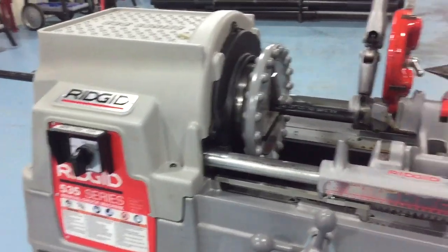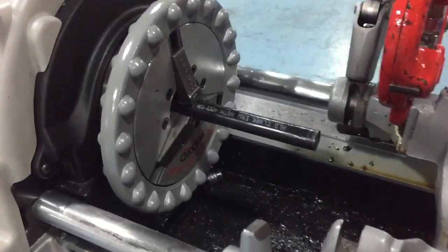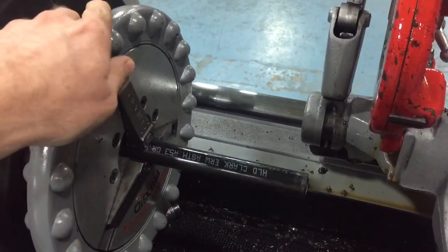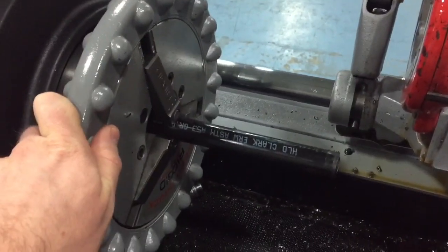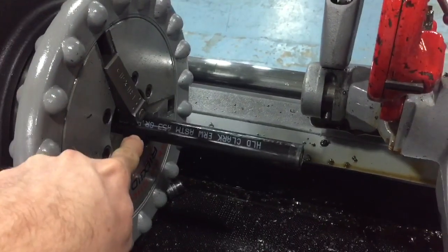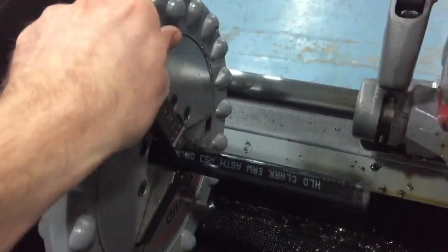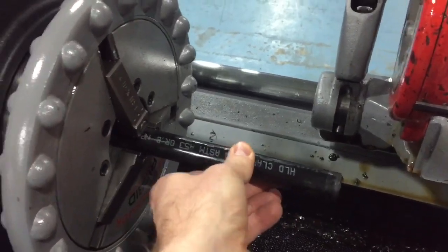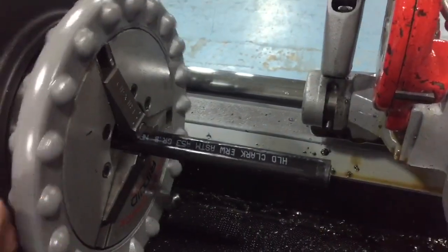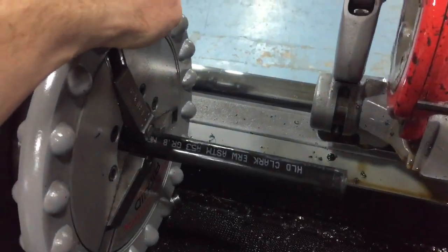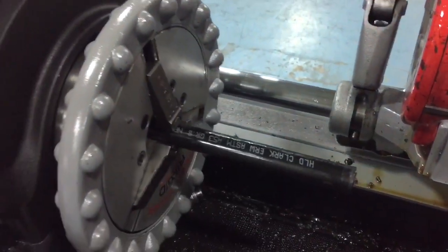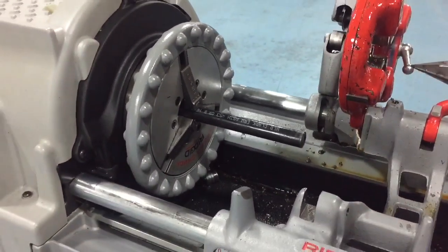So what we're going to do first, I have the pipe in place here. It has a chuck. We hammer it and it grips the pipe, the chuck right here you can see. And so if I just hit it and back it off here, then I can now move the pipe around. And then when I want to clamp it again, I just take the wheel and I hammer it into place, and now the pipe is secured, and the threader can then turn the pipe.